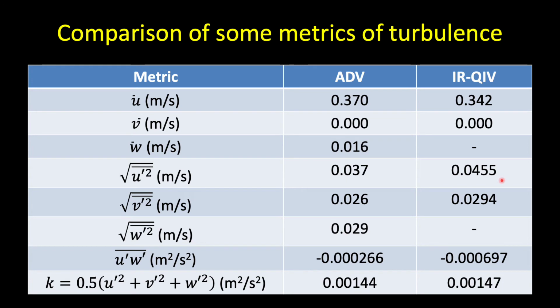We see that the turbulent intensity on the free surface is larger, as we would expect by the splats, but if we shift to a kinetic energy perspective, those splats should contain the same kinetic energy. It's just characterized in different components. So as the three-dimensional eddy moves to the free surface, absent a dissipative mechanism such as surfactants, we expect the total kinetic energy to be the same, and we see in fact to the third decimal place that it is. Here we see that the Reynolds stress on the surface is about a factor of 2 greater or more than at depth, but both show the same sign and same order of magnitude.